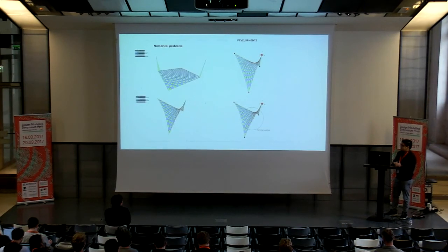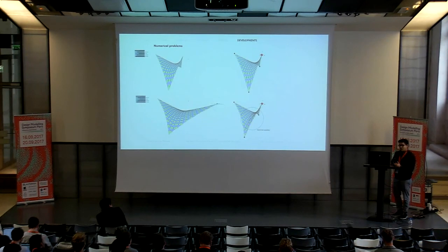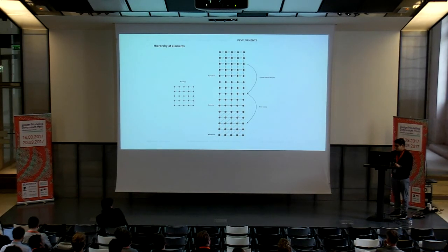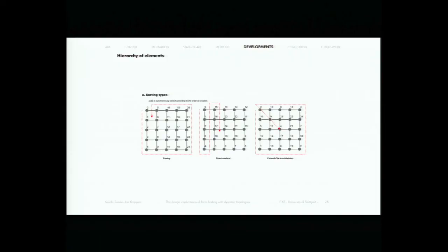The problem is that, despite these elements having different topological requirements, surface elements tend to be numerically unstable when active modeling is enabled. To face this problem, we propose to conduct initial studies on shape exploration by using systems of cables or springs, and as soon as a satisfactory shape is attained, to dynamically shift to surface elements. This is only possible because quad elements can be easily converted into triangular ones.